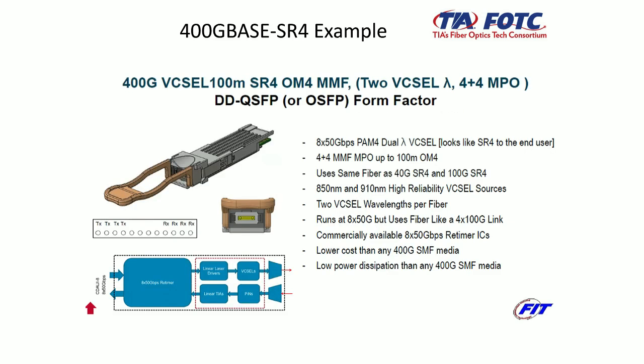So here's one example. I could do a 50 gig line rate that would be encoded with PAM. So I have a 25 gig base rate encoded up to a 50 gig net line rate, and then having 4 colors with 4 positions gives me 400 gig. And this could be a potential transceiver. This might be one of the first ones that show up.